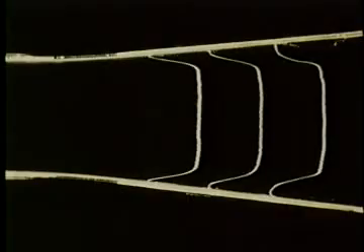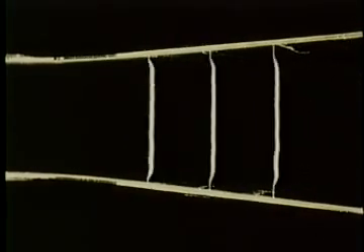The point on the wall where the fluid in the upstream boundary layer meets the fluid from the region of flow reversal is called the separation point. The wall shear stress is zero there. Here, the point of separation of the laminar boundary layer is near the first wire.